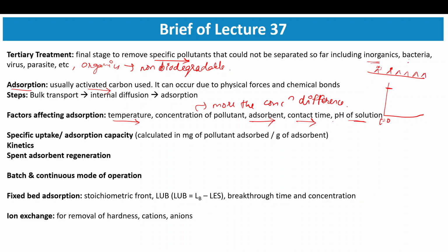Initially all are vacant, so more adsorption might occur, and there will be a steep decrease. Then as the time progresses, these vacant sites are used up. Let's say this pollutant has to get adsorbed. It has to see which active site is vacant, so there will be a time where the rate of adsorption will reduce.